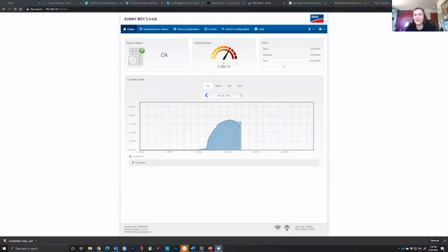All right, so this is a graph showing the solar energy production from my roof today. I have a 5 kilowatt array, and is a kilowatt energy or power? A kilowatt is power. And so to get energy, you take power and multiply it by time. So kilowatt times an hour equals a kilowatt hour of energy.